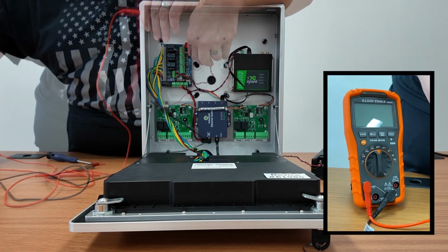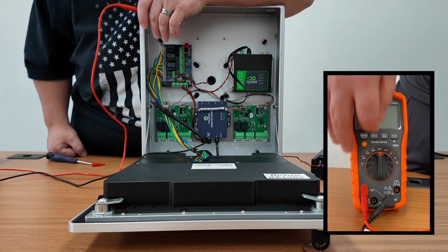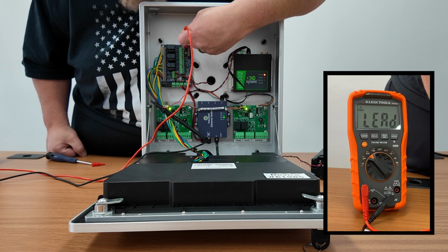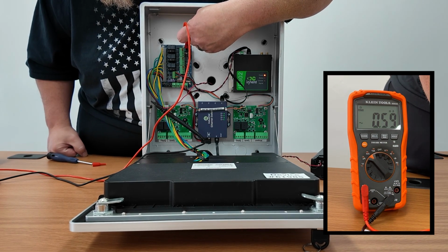Connect the disconnected wire to the negative lead of the multimeter, set it to the amperage mode, apply power, and observe the reading. For our WXL product, the maximum current draw should be around 2A, but the reading may be limited by the power supply's capacity.